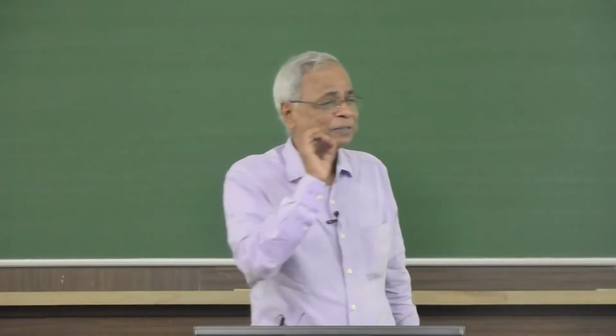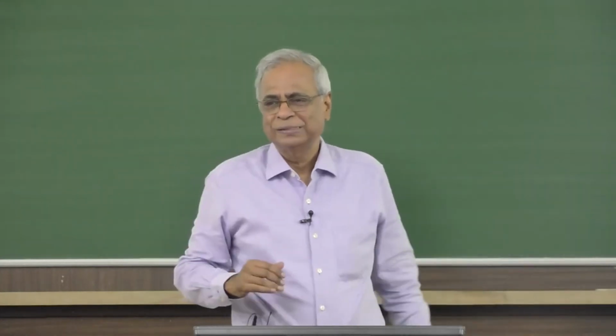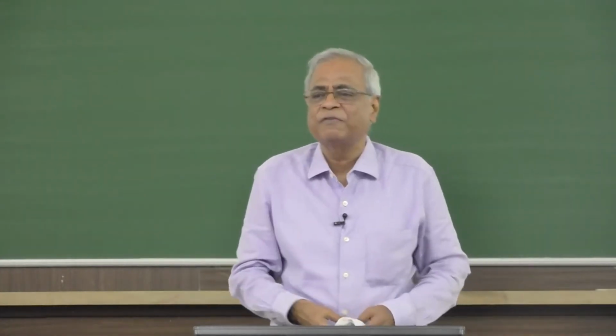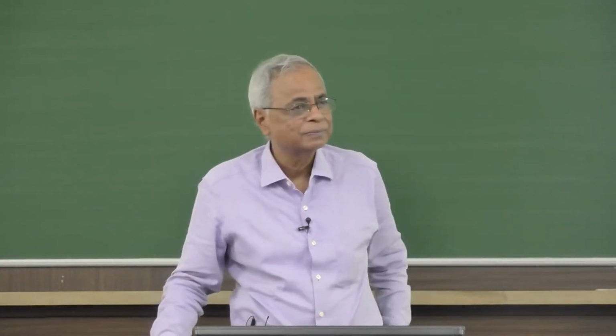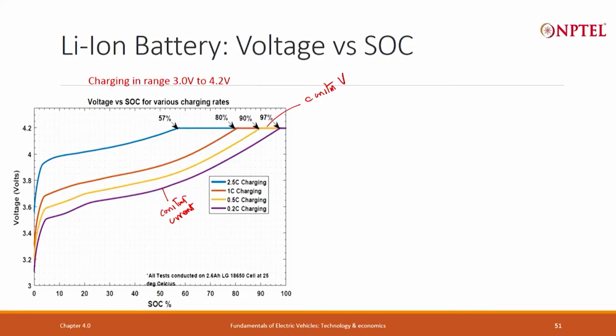So, first important point that I want to make, fast charging does not charge the battery full, it can only charge in this case 57.6%. That is all that it will charge. For some other cell, you may be able to charge up to 70%, 75%. So, that will depend on cell to cell. So, this is what you can charge. This is the voltage versus SoC. Okay.